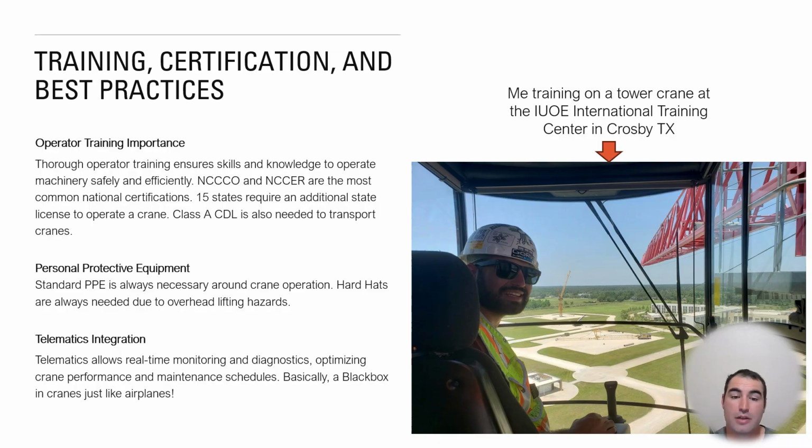So, training, certifications, and best practices of crane operations, right? Thorough operator training ensures skills and knowledge to operate machinery safely. The NCCCO and the NCCER are the most common types of national certifications, and there's 15 states that require a state license to run a crane. And also most companies require a crane operator to hold a Class A CDL. Then PPE, hard hats, safety shoes, all that's extremely important around cranes.